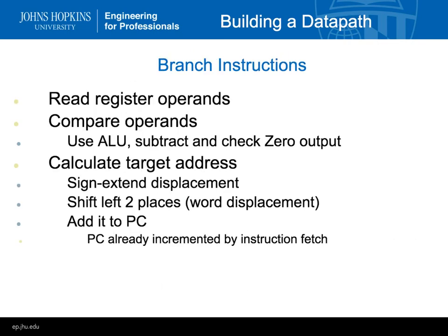So if you recall what happens in a branch instruction, BEQ, branch on equal, is going to take 2 register values and compare the values in these 2 registers, and if they are equal, there's a 16-bit value. The lower 16 bits are an immediate value, and it's going to increment the current program counter by this amount.